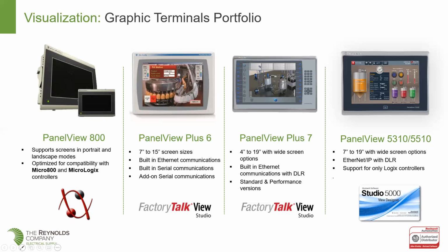We look at the PanelView 800 family, and those are really designed to be smaller machine-level control HMI, and they work with the Micro800 and the MicroLogix controllers, as well as the lower end of the CompactLogix line.